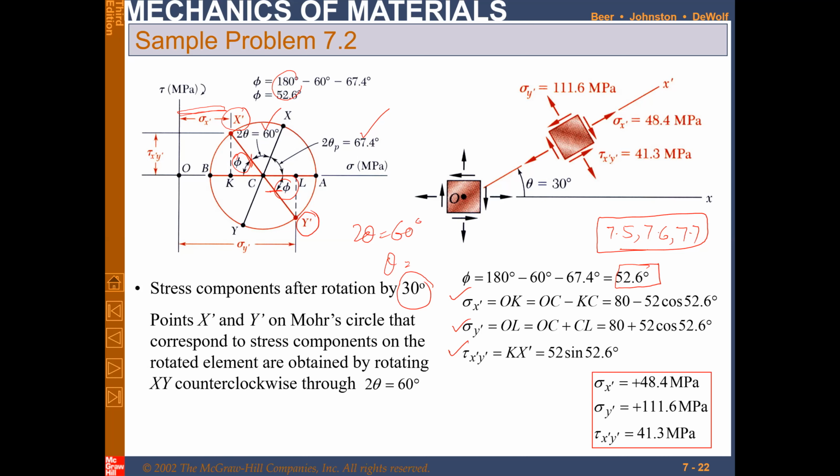That loading condition obviously will be given to you in terms of sigma x, sigma y, and tau xy. So you will draw the Mohr's circle. Mohr's circle will give you an overview from which you can quickly see what the sigma max value is, what the sigma min value is, and then you can accordingly see what the tau max values are. And from that, if your allowable stresses are greater than the maximum tau and maximum sigma values, you are safe. If not, then you are not safe. So this is ultimately the objective of this whole scenario.